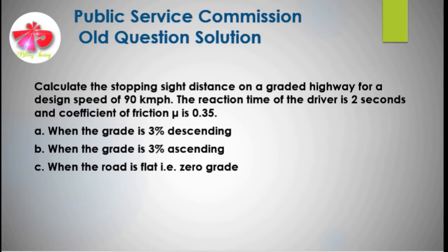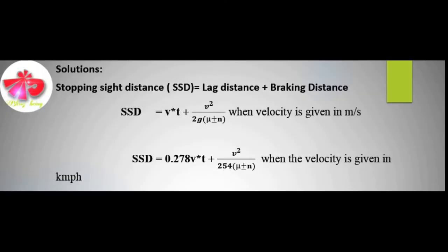Stopping distance is one of the important measures in traffic engineering. It is the distance a vehicle travels from the point at which a situation is first perceived to the time the deceleration is complete. Drivers must have adequate time if they are to respond suddenly to a situation. Thus, in highway design, sight distance at least equal to the safe stopping distance should be provided. We will go through the solution of this problem.